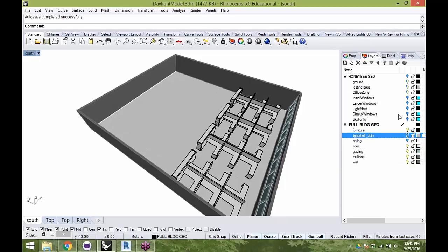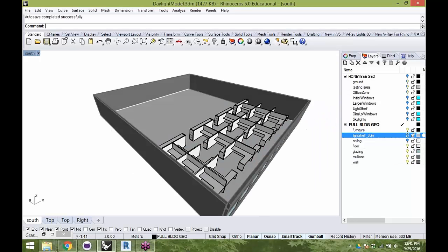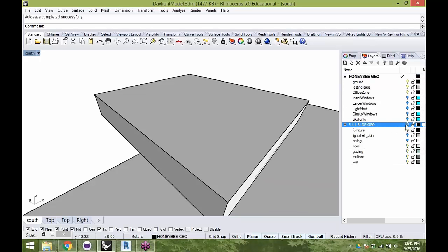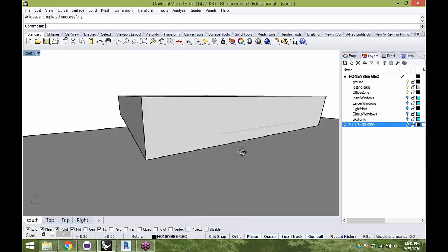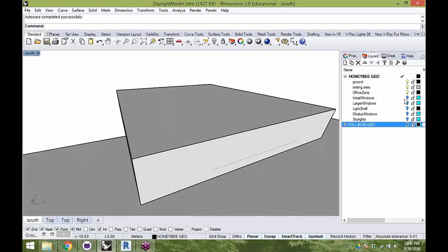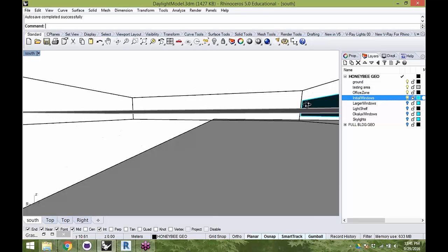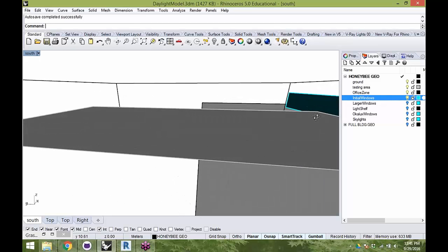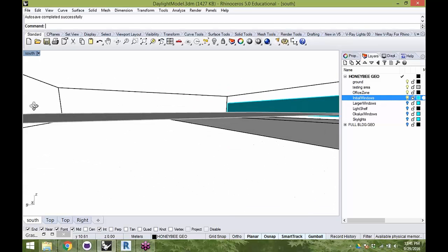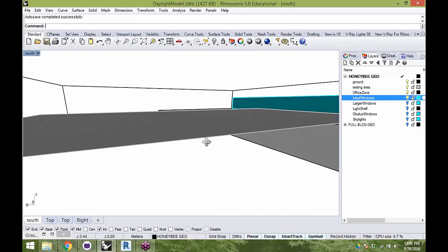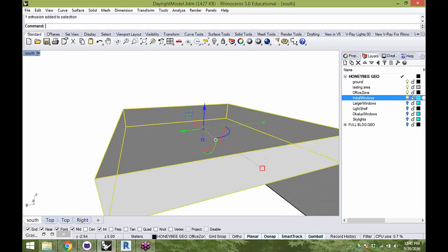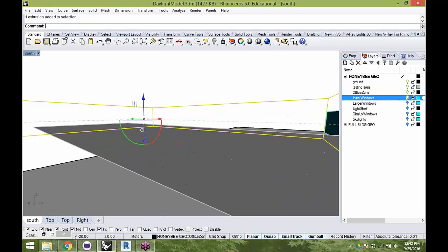All right, so the first thing I'm going to do, you will notice that I've modeled all the detailed geometry, and we certainly could run our daylight studies with all this detailed geometry, but for the sake of time, just because this is a 2-hour workshop, I'm going to be working with some simpler geometry here. So basically, we're going to start by assuming a box instead of all the detailed geometry. And you can use the same methods I'm showing you here to run the detailed geometry if you want. But we're just going to evaluate this box.